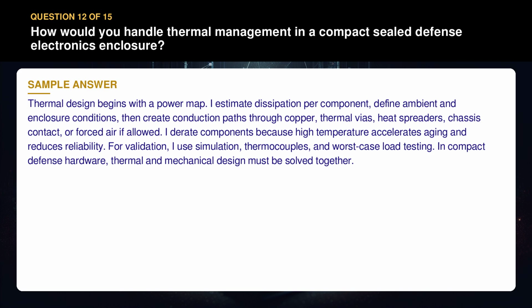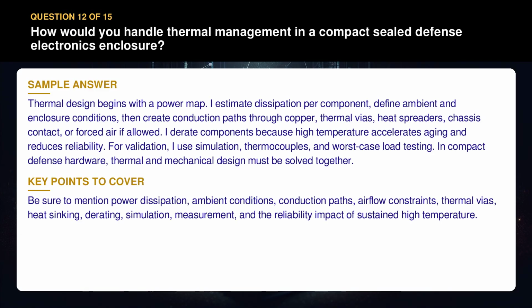I derate components because high temperature accelerates aging and reduces reliability. For validation, I use simulation, thermocouples, and worst-case load testing. In compact defense hardware, thermal and mechanical design must be solved together. Be sure to mention power dissipation, ambient conditions, conduction paths, airflow constraints, thermal vias, heat sinking, derating, simulation, measurement, and the reliability impact of sustained high temperature.